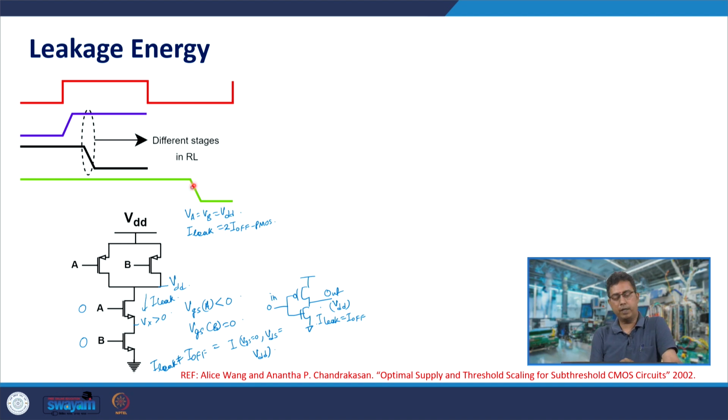Switching happens in a well designed circuit only for an insignificant part of the total time period. Typically, in an above threshold circuit, we would observe that the logic depth has a value of 15 or so, and in a near threshold voltage circuit, this would be some 7 or so typically. So, why would it be smaller in near threshold circuits? Because the delay of each logic gate is now quite large. So, that is why the logic depth is usually smaller. We will discuss this later.